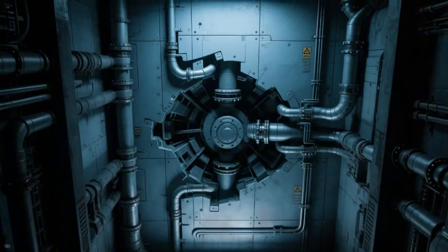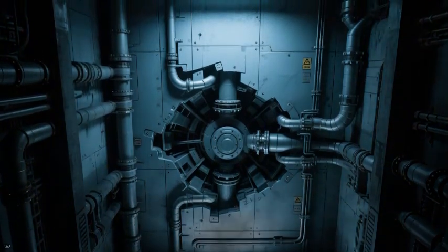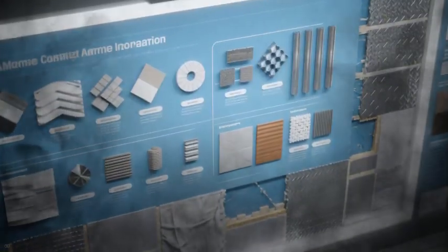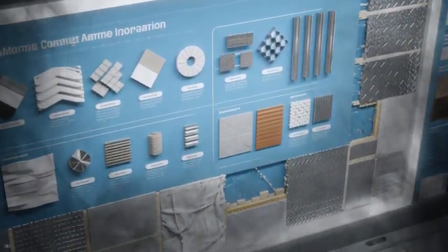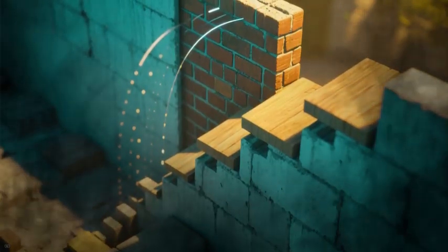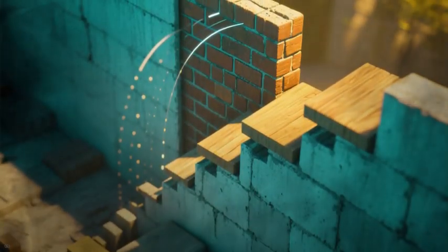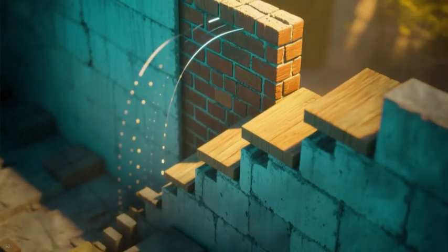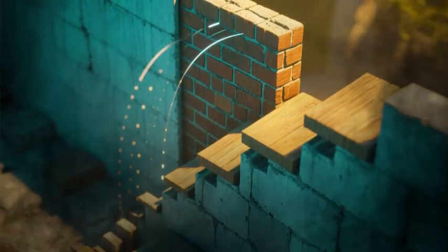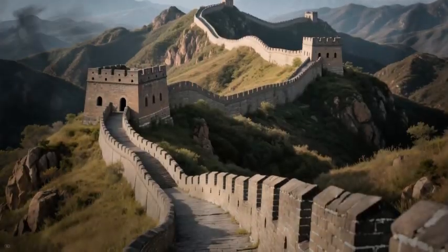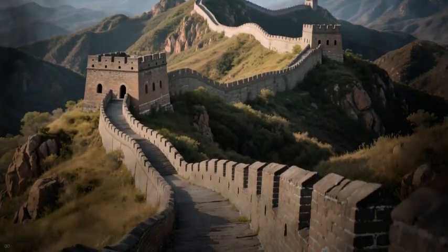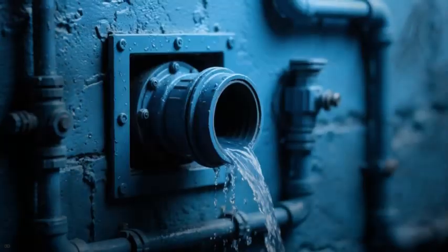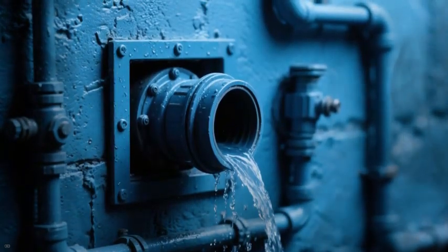The internal core of many Ming wall sections remained rammed earth. This combination of stone, brick, and compacted soil balanced strength with efficient use of materials. Brick and stone provided durability where it mattered most, while the earth core reduced the need to transport large quantities of heavy materials. This hybrid structure allowed the Ming dynasty to construct long stretches of wall that were both sturdy and economical. Drainage systems represented another engineering advance.